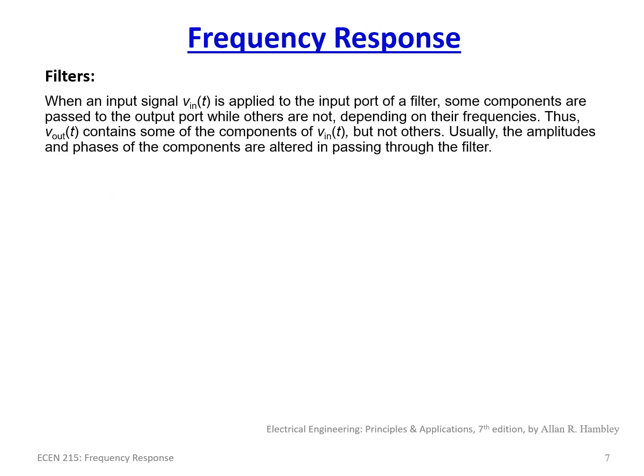So this brings us to the concept of a filter. As we were just showing in the previous slide, we had an inductor and a resistor circuit, and as we swept the frequency from 0 radians per second to infinite radians per second, the output voltage, with a normalized input voltage, went from 1 volt all the way down to 0 volts. In other words, we went from maximum amplitude all the way down to no amplitude whatsoever. It was completely cut off.